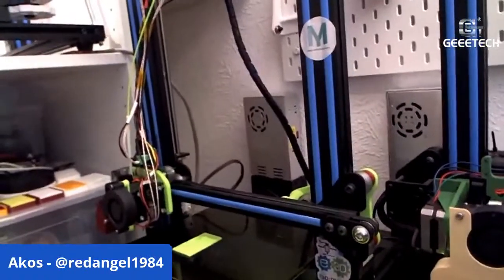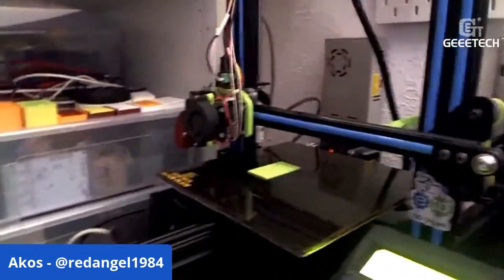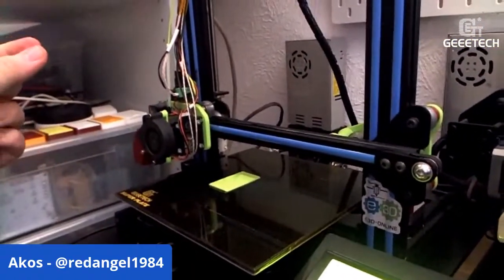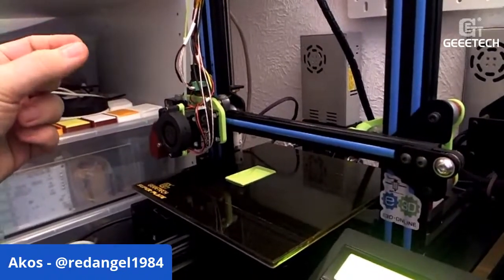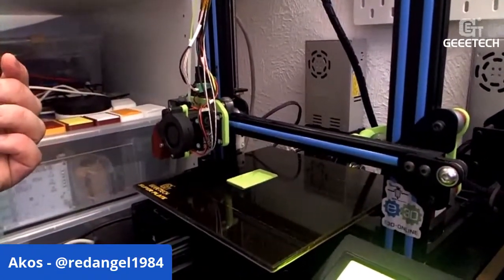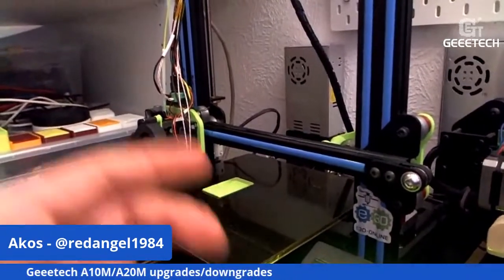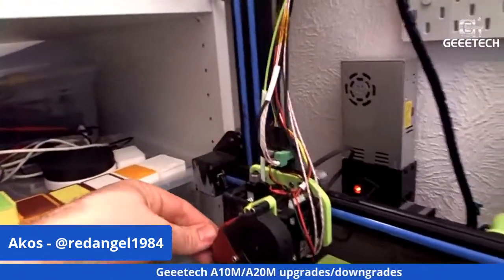So the first and easiest upgrade to a printer is the nozzle. You can upgrade from the standard 0.4 millimeters, which I can't show you, it's too small, to a smaller nozzle, and that will bring you much more detail, but less speed. And if you upgrade your printer to a bigger nozzle, let's say 0.6 or 0.8 millimeters, the detail is not so great, but you can print twice or much more faster. So that's one of my upgrades, the nozzle size.